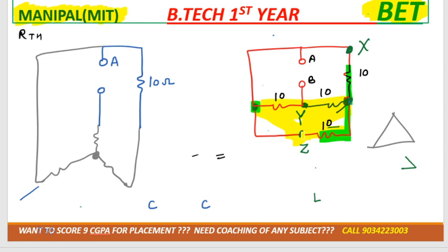We are converting delta to star. So it would be how much? 10 into 10 divided by 10 plus 10 plus 10. That would be 100 by 30. Sorry, 10 by 3. 10 by 3.